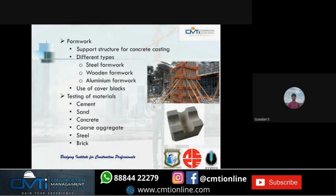There are various materials that must be tested compulsorily before use: cement, sand, concrete, coarse aggregate, and steel, brick. For cement, there are various tests, such as the soundness test. For the soundness test, in the field also we can test by inserting our hand inside the cement or throwing the cement in a bucket. For sand, we have specific gravity test, bulking test, sieve analysis test, etc.